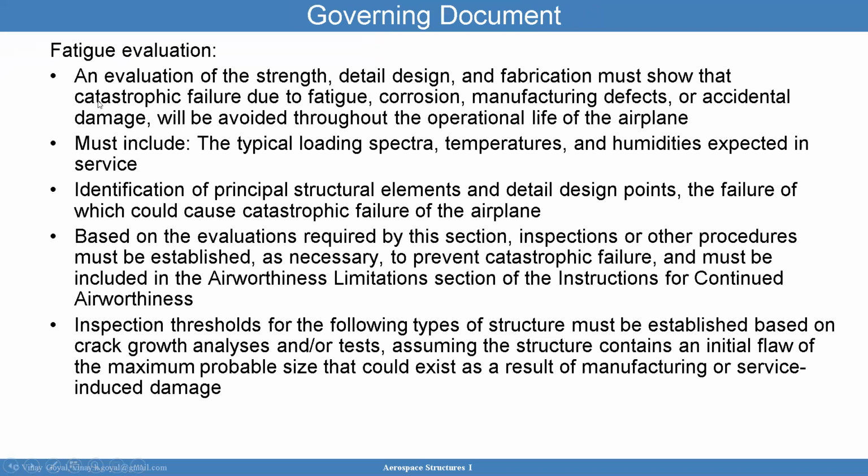The fatigue evaluation has to be conducted, and I already covered a lot of this, so I don't want to repeat it again, but you want to make sure you implement inspection thresholds for the following types of structures based on crack growth analyses, assuming that the structure contains an initial flaw and is of the maximum probable size. And that's going to be related to the manufacturing process. So that's a very important consideration. You have to identify the principal structural elements and design detailed design points for which the failure of those components could cause catastrophic failure of the structure.